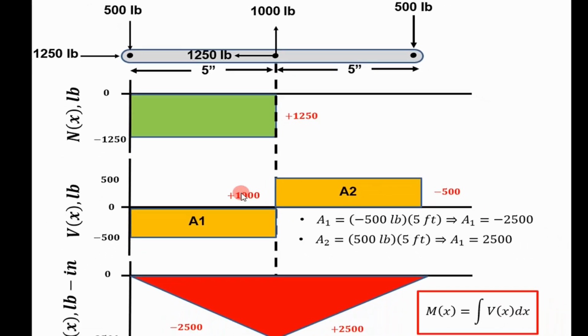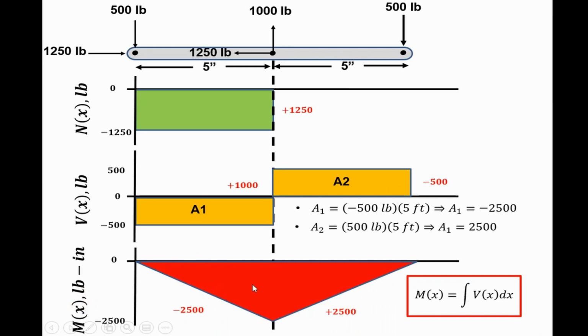And so now our bending moment diagrams. Well, if you recall, bending moment is actually going to be the area under the curve of the shear force, and it's given by this expression. This is the mathematical expression. The bending moment along this axis is going to be the integral of the shear forces along this axis.